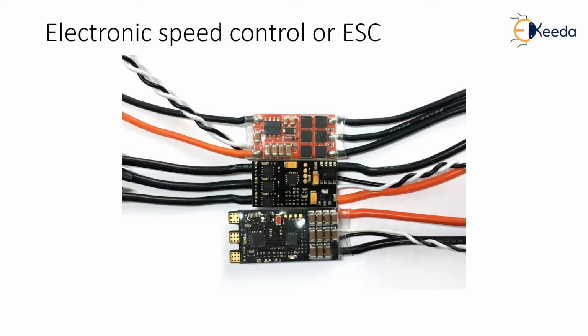Multi-rotor aircraft are controlled by adjusting the speed of the motors and in turn the speed at which the aircraft's propellers spin. It increases or decreases its height by increasing or decreasing motor speed. It flies forward by increasing the speed of the rear propellers and vice versa, and goes left by running the right hand propellers faster. Turns are achieved by taking advantage of the fact that two motors spin clockwise and two counterclockwise, and then precisely adjusting the speed of individual motors.